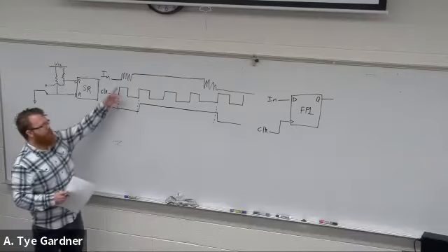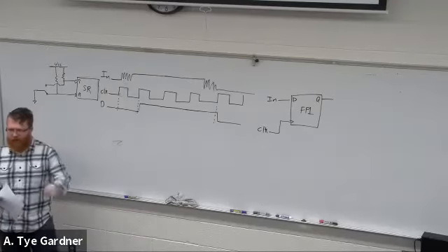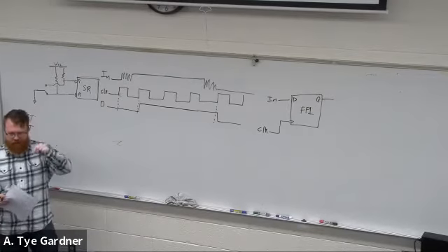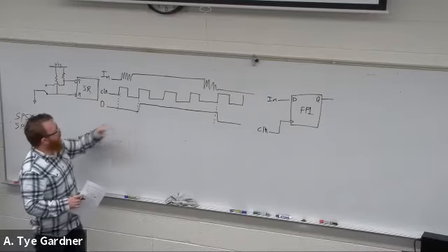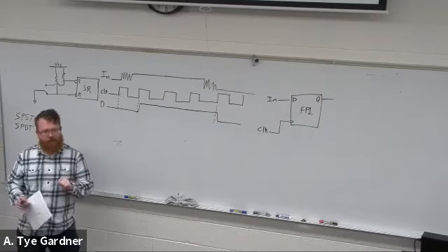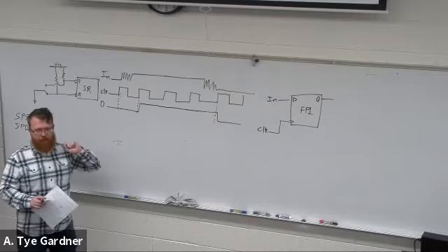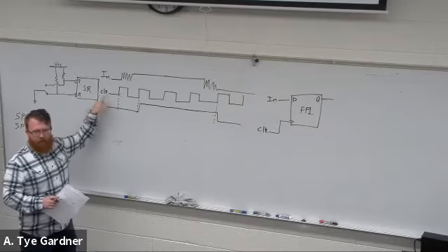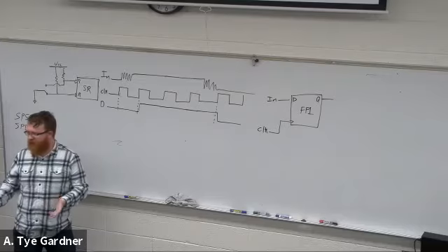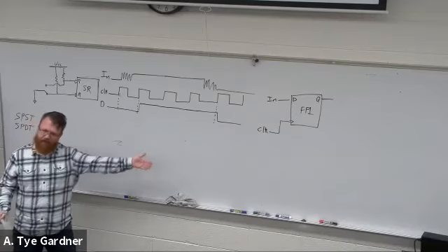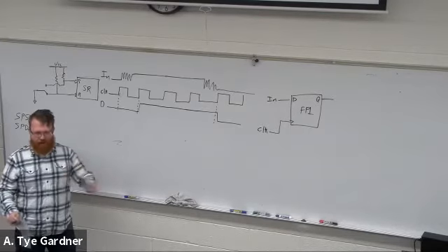So, I mean, depending on your circuit, right? Different switches have different bounce characteristics. The littler they are, the better they tend to be. But anyways, I'm not a mechanical engineer. I don't know all the details of it, but it can be an issue. So you want to make a slow clock. Making a slow clock takes a lot of circuitry, right? Because it's a clock divider. Divide it down, divide it down, divide it down, divide it down. Every time you divide it down, you have to add more logic.